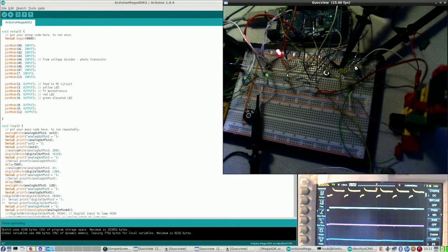Select 2 and okay, it is now at the line itself right here, but it is still at 2 volts. So what's wrong with that? Either there's something wrong with the LED or there's something wrong with the port, and I think I first will replace the LED.